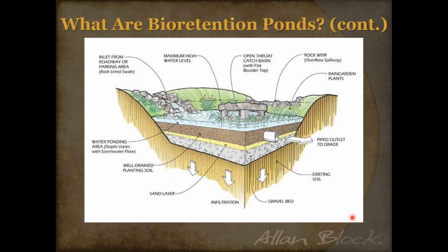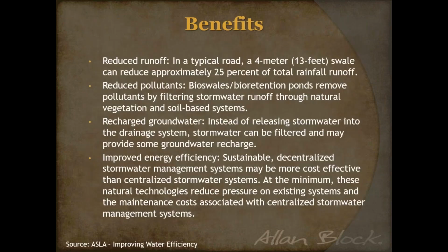So there are a lot of different ways a bioretention pond can look, but they're always going to come down to those basic elements. Where those are, the depth of those, or how they're positioned will depend on the design. But we know the benefits. There's a reason why you guys as engineers are getting asked to do more of this stuff. Let's face it, you're doing a lot of redevelopment or increased land use, and so now you've got more impermeable surfaces and that additional watershed to worry about.